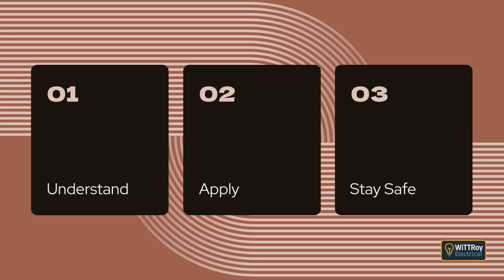Clause 2.3.4.4 Identification. All isolating switches in this clause must be clearly and permanently identified so anyone can see exactly what they isolate. If the control for an isolator must be placed away from the switchboard, then a clear warning notice must be installed, describing the operation of the isolator and the circuits it affects. The goal is to prevent a situation where someone misunderstands how the isolation works.